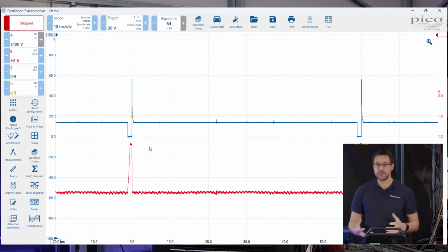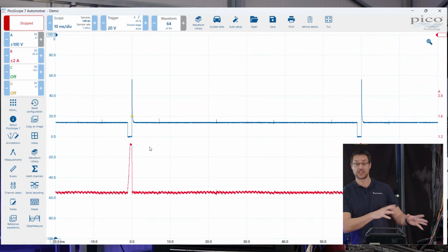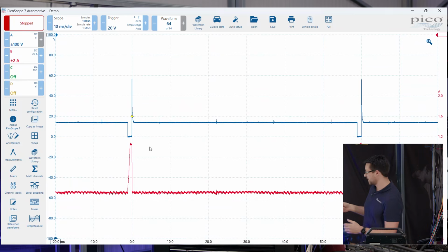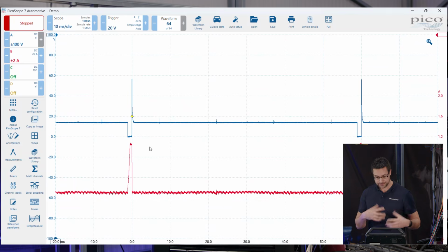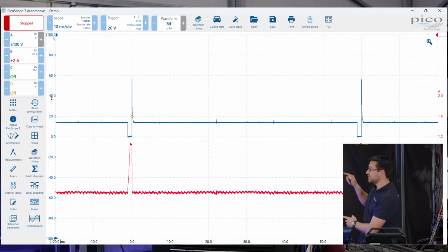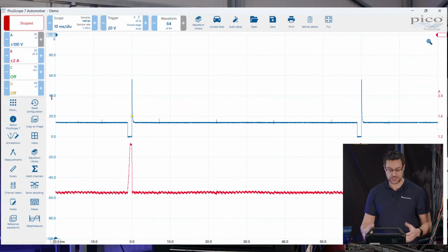It's not often that we need to use the bipolar part of the waveform. Where it is important though is if we're using a current clamp, for example, and maybe you've got it on the wrong way round, so we actually see this but flipped around the other way, it's inverted. So now we understand our channel ranges, or our vertical axis.